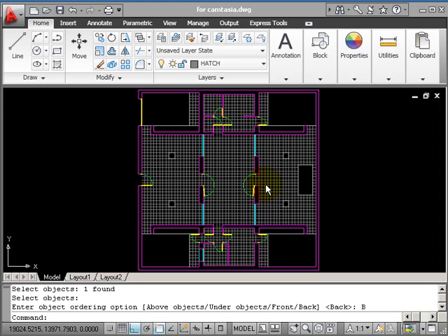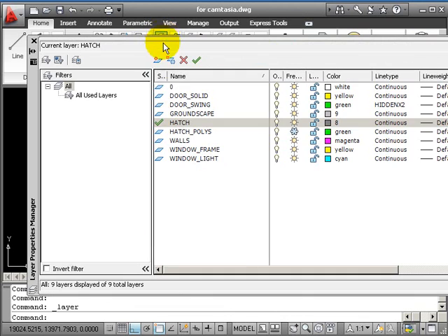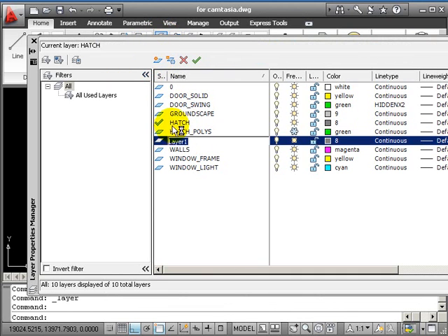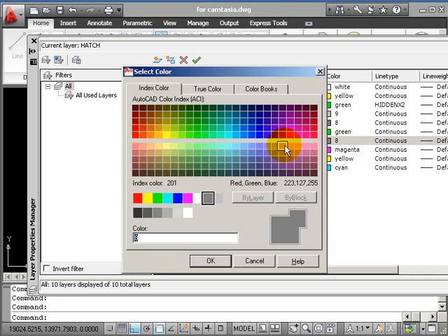We're going to move on to drawing a section through the building. Now, let's create a new layer. Let's create 3 new layers actually. First one, I just want to create a layer that we're going to use for some annotation. So let's just call this annotate and make this layer color yellow. And OK.